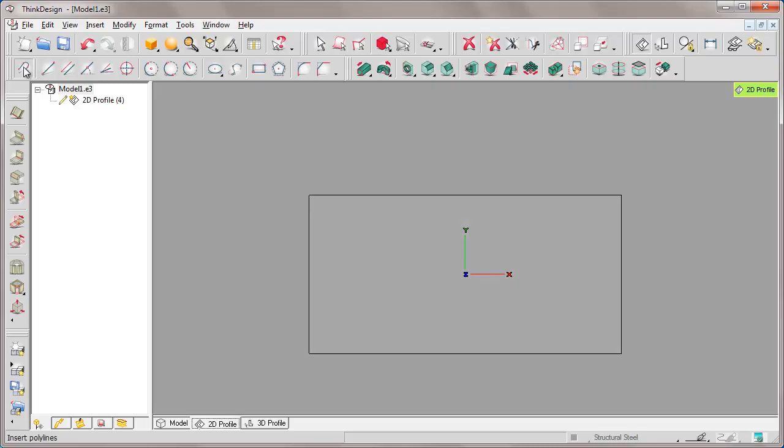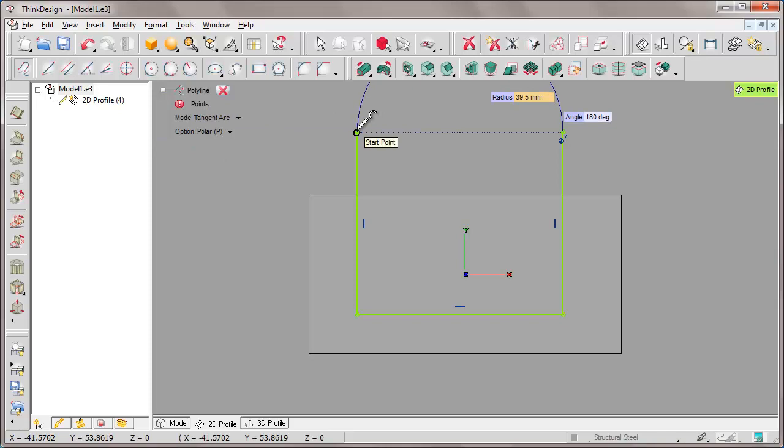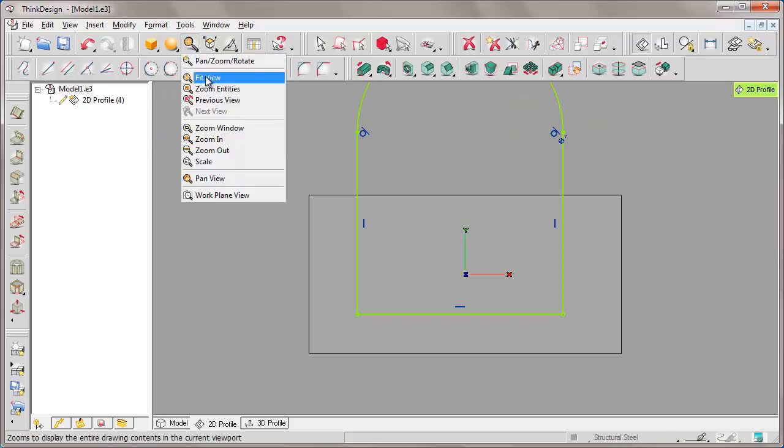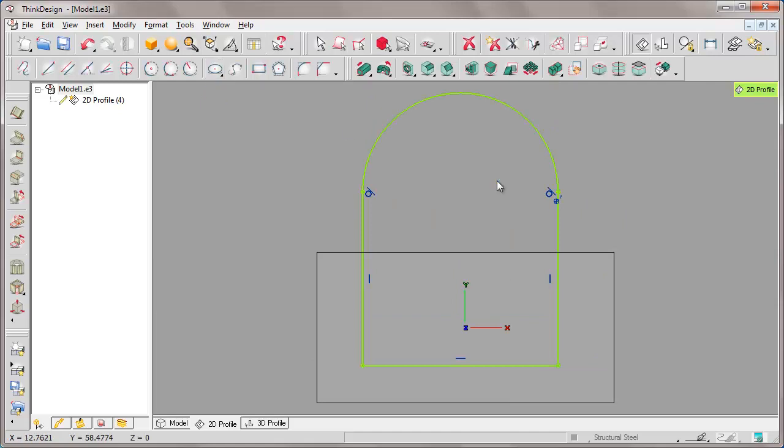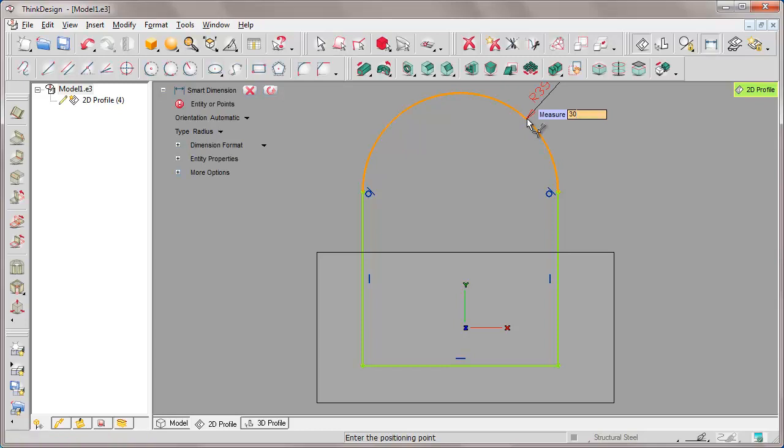Let's create directly in profile environment our shape with a so-called sketcher approach. Therefore, we actually make a sketch of the shape we want by the polyline command. Then we move from line mode to tangent arc mode. The program already inserts the geometric constraints, detecting them during the construction. So vertical lines because we sketch them vertical. The arc already put the tangency constraint and so on.